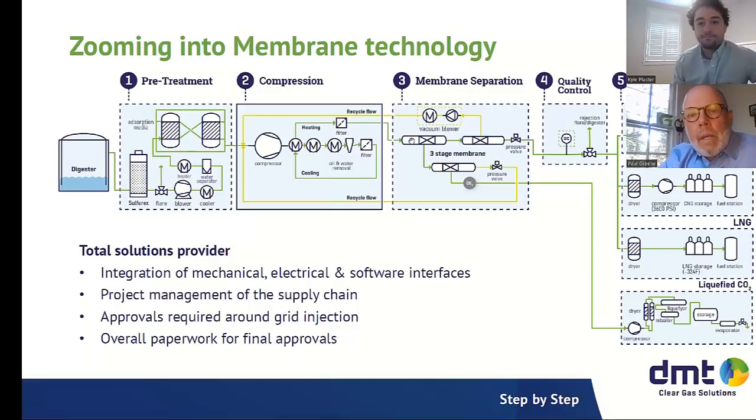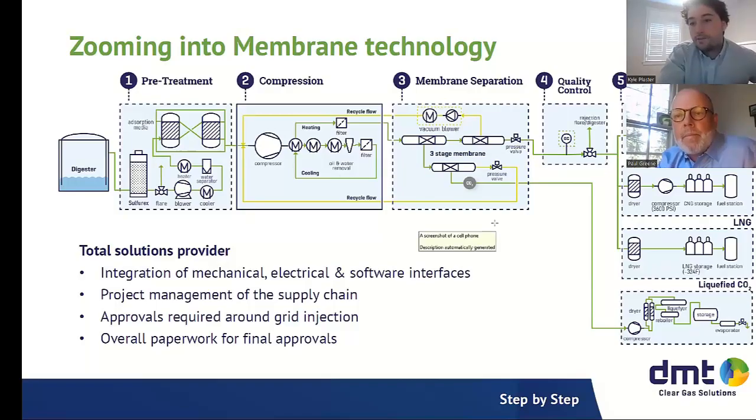Yeah. Okay. So here's the 3-stage operations. So coming through stage 1, tell me about the vacuum blower pulling on stage 2. What does that do? Yeah, so how the membranes work again is a pressure differential. So we might not have as high a pressure going into stage 2. So to help that pressure differential, we'll actually have a vacuum on the permeate. So the gas is more apt to permeate through. So that's just to increase that pressure differential. So that's not so much about getting the gas back to the compressor. You're just helping the performance by pulling on the membrane a little bit. Exactly. Yep. Got it.